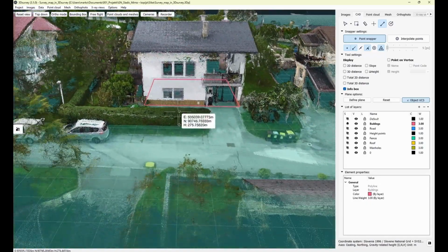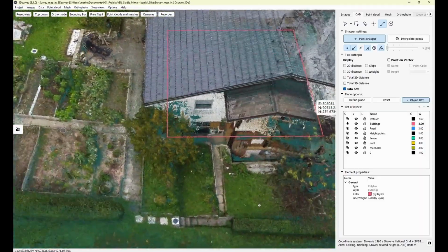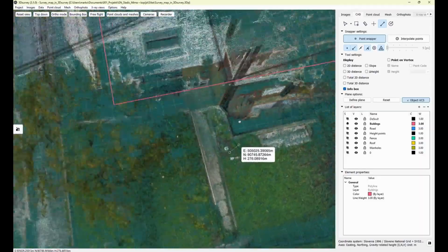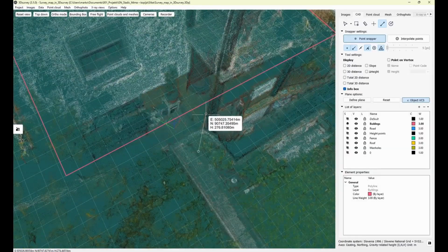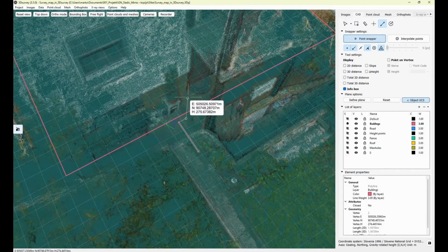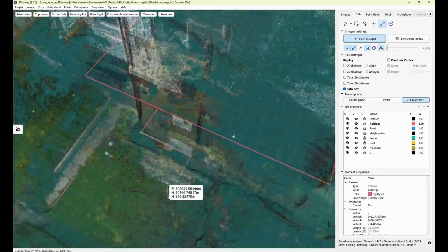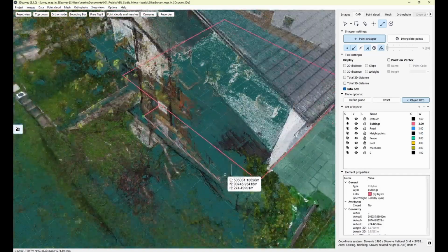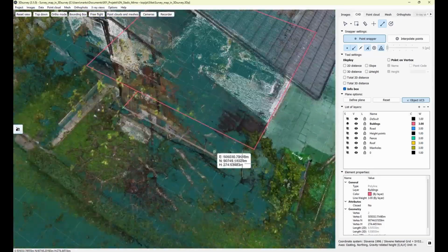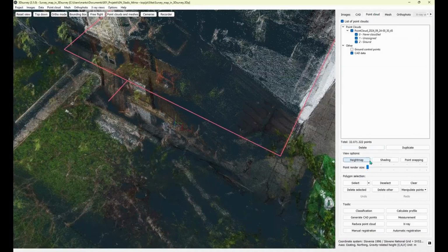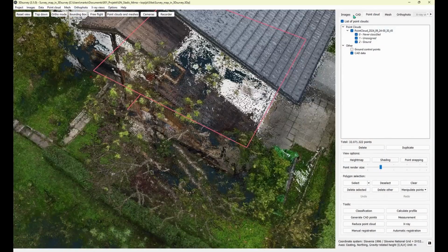In this workflow, I generated the perfect building footprint. Let's now also add the stairs. I'm still in perpendicular snapper mode. A lot of data is probably missing here. I will go to point cloud, make these points a bit bigger and go back to CAD.